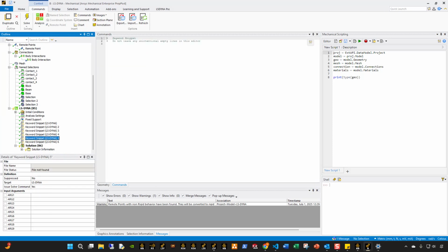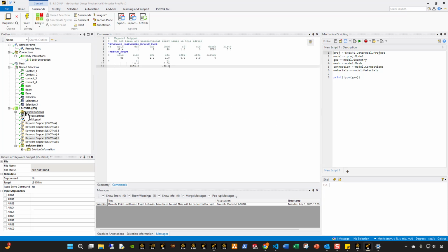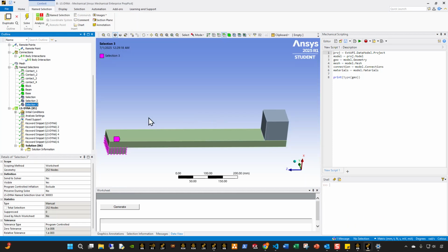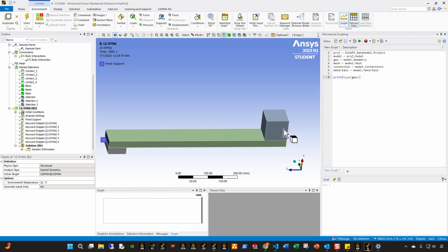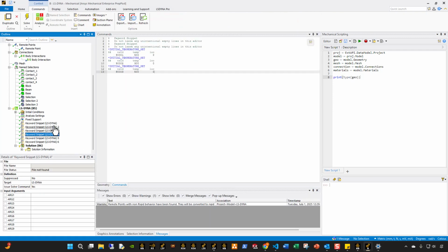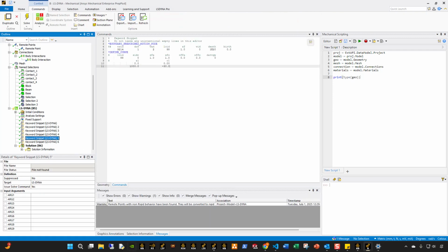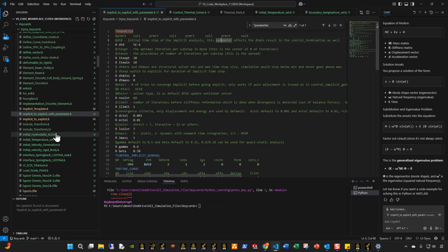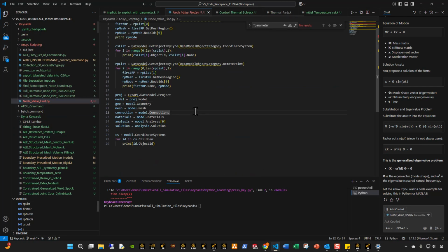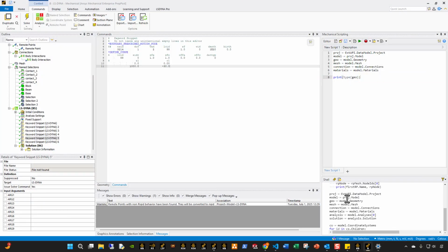And then of course in here, what I wanted to do is to generate a boundary condition to move that remote point down by 30 millimeters over 1,000 seconds, right? So I'm gonna move that block down over 1,000 seconds. Now this node number right here is not gonna be 23214. So what you do here is use the common script I've been using almost every day now. Use this little quick script to find the actual node ID, which is actually 3214 because of the nature of the mesh. So you see how this remote point has an ID of 3214.